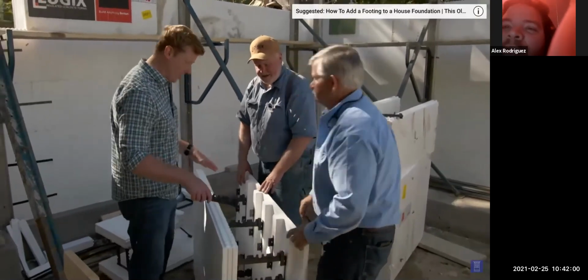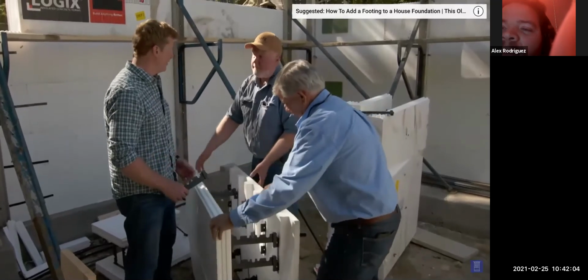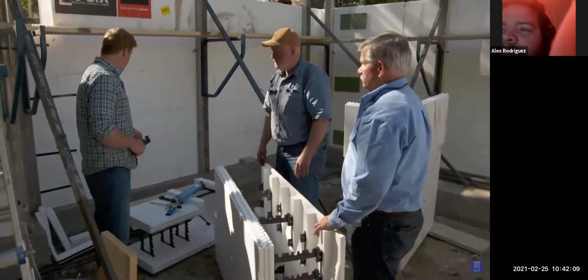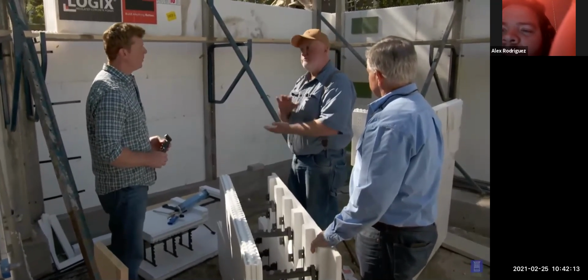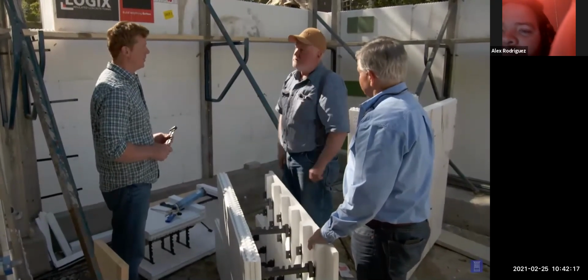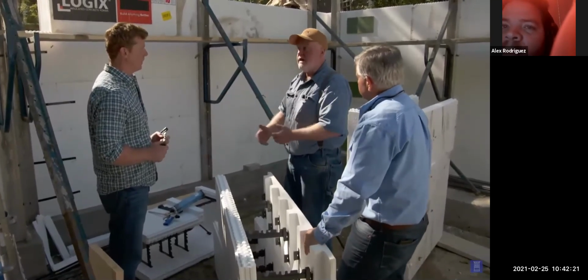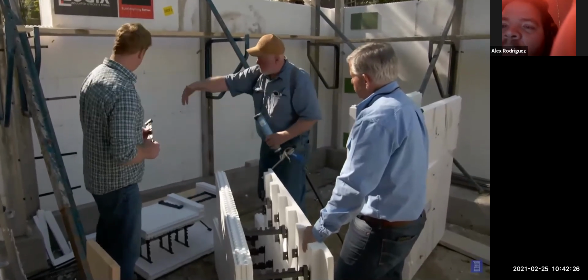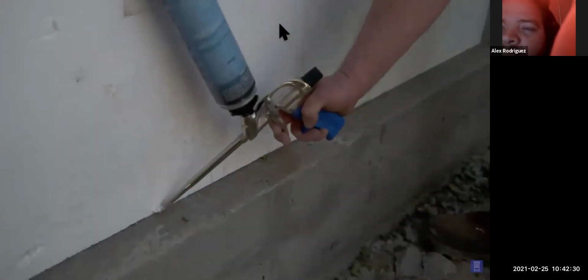So you snap those all together, and then you've got yourself what? An individual, what do you call this? This is a form. How are we affixing the form to our concrete footing right here? Well, the first thing we're going to do is cast a footing that's perfectly plumb and level because we don't want this thing to shift and move. Then we'll snap lines on it just like a standard footing. And then we're going to use an adhesive. Once we've assembled them in place and set them to the line, we'll put a bead of adhesive right along here.